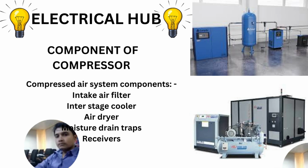Components of compressor. The compressor air system contains intake air filter, interstage coolers, air dryer, after cooler, moisture drain traps, and receivers. The intake air filter is to clean the air before entering into the compressor so that it cannot damage the pistons and valves. Number two is the interstage cooler.